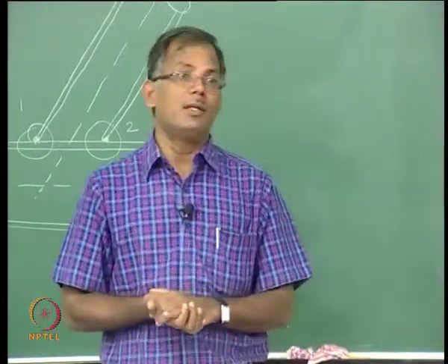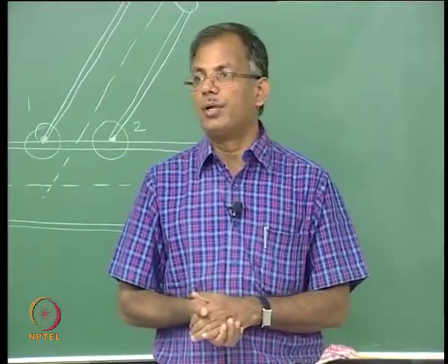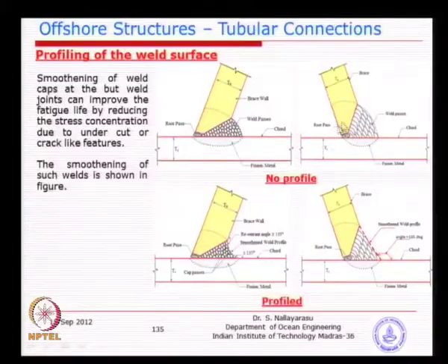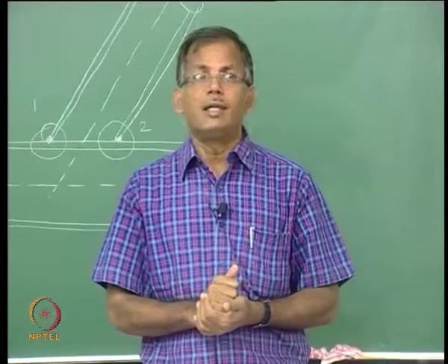Why is it not recommended? Basically doing this is a very troublesome process, because it is time consuming. For example, if you remember, from here to here the distance could be 100 mm or maybe less than that, 100 mm all around the brace, and taking away the material by simple manual grinding can take several days.